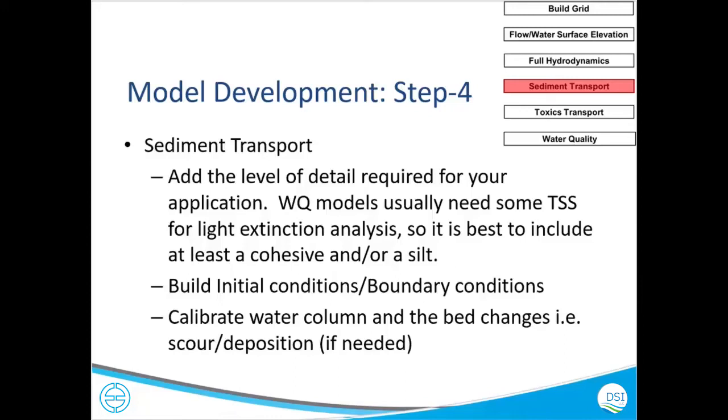So we'll talk more about sediment transport, how it's done in day 3 and day 4. Then you need to build your initial and boundary conditions, and then calibrate your water column TSS, total suspended solids, with your measured data, and see if your model is doing a good job or not.